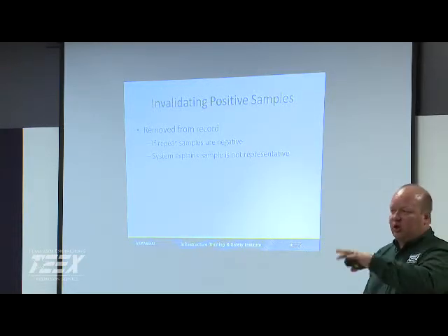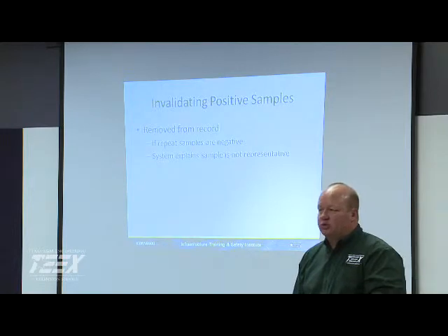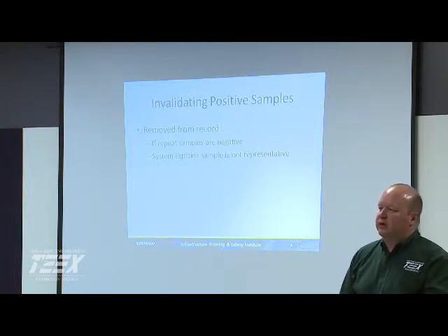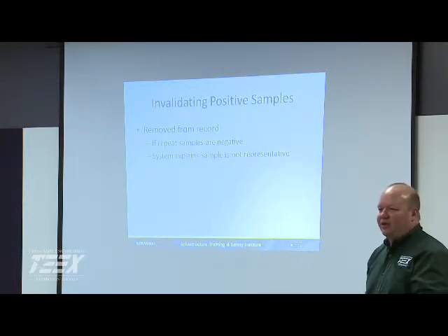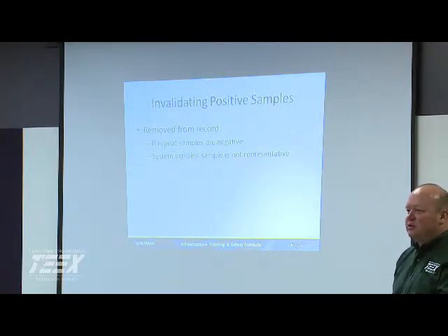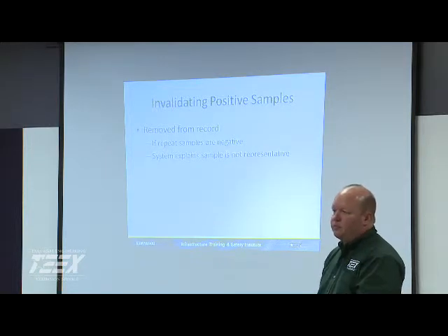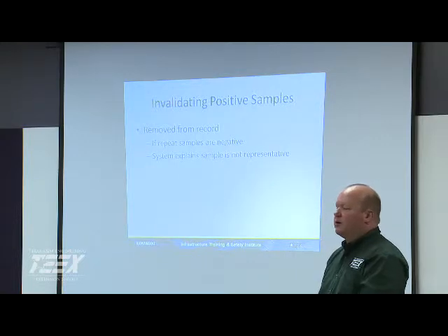Yeah, that's understood. So do y'all actually go out if there's repeat samples to be pulled? No, not enough time. We just talk with the water system about what you find and all that. If there's a real serious issue, like multiple positives, we'll probably go out and pull samples ourselves to see if maybe there's a sampling technique problem or something like that. But for the routine positive, we usually don't go out and do the sample. Right. Understood.